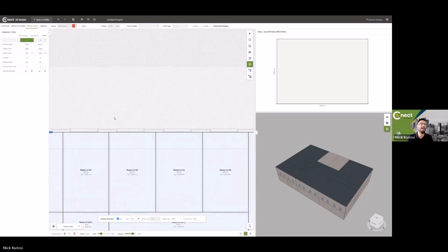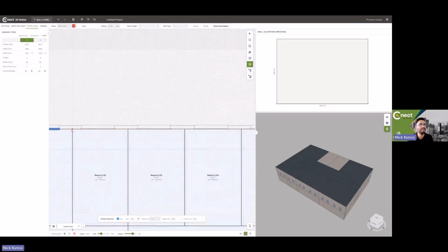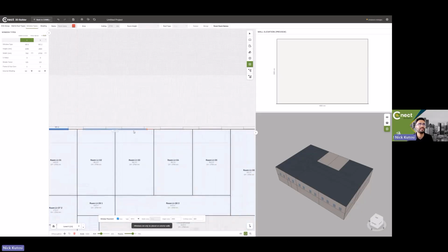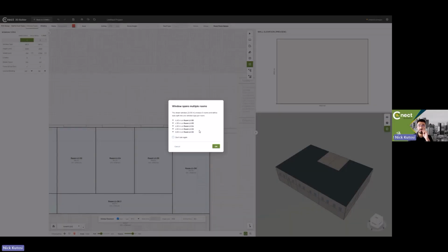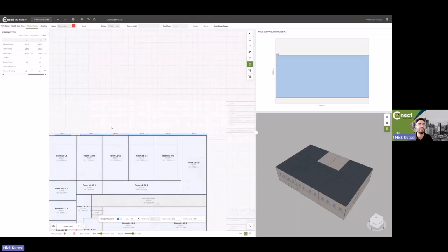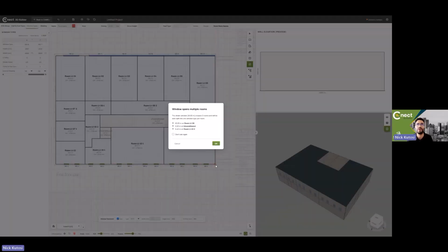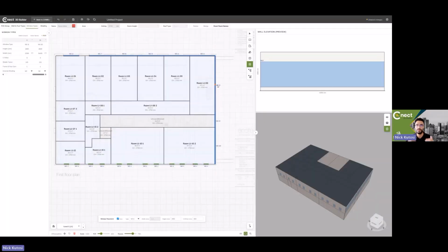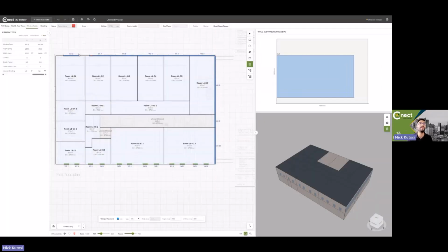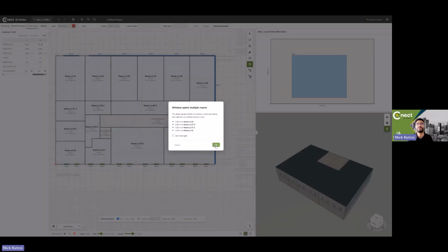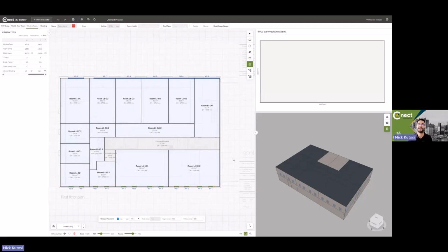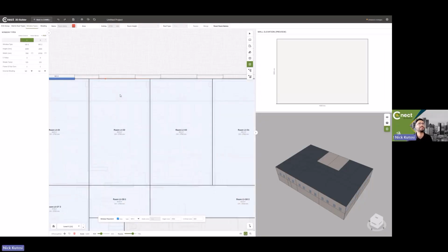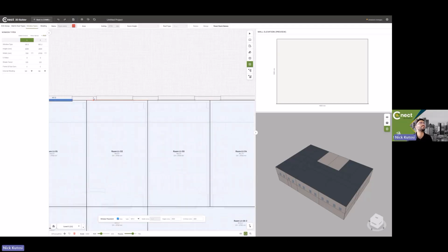And a nice feature of that is if we click, say, here on the wall and we draw all the way across, it will automatically create window types and split at the room boundaries. So you can see this can be a quick way of doing floor to ceiling fully glazed windows and creating a window type for each of those. We'll go ahead and undo that. So Control Z at any point undoes your last action, because that's not what we need for this project.